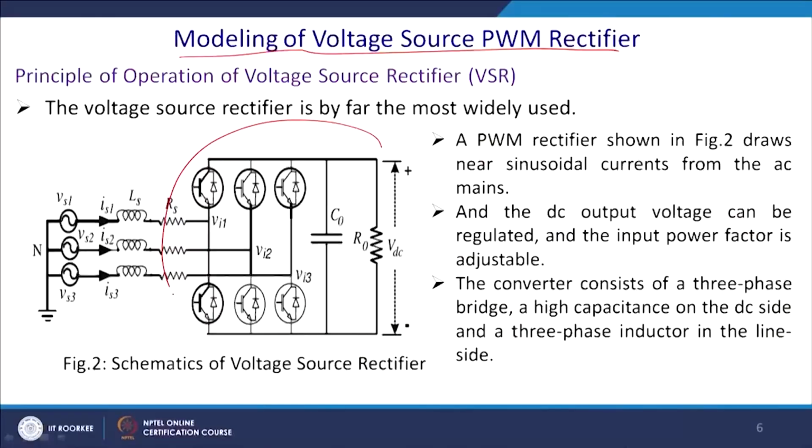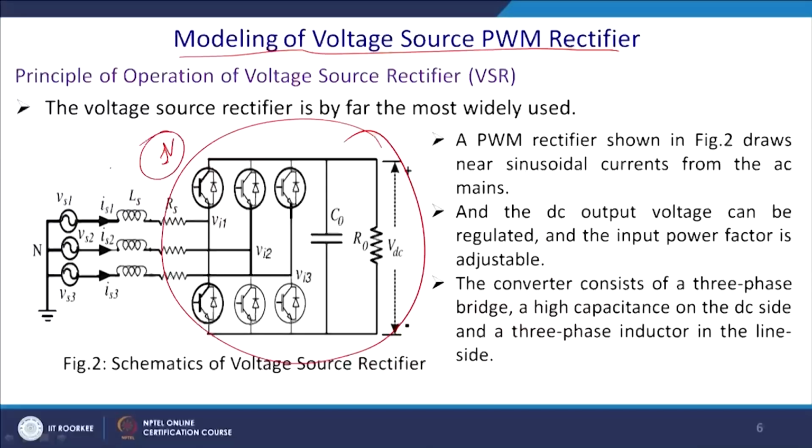So, it is one of the main part. Instead of the diode bridge rectifier, we will use this PWM rectifier. Another issue is actually the power rating of the diode. Once high current flows through the diode, this power diode will drop around 1 volt. In that case this drop is quite huge, and sometimes to negate those drops we also use synchronous rectifier,